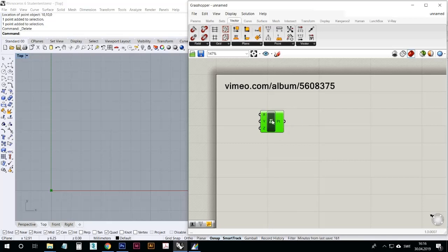Right? And after you hovered the title, I want you to hover the output so you know what it's actually giving you. If you hover here, it says point. It creates a point coordinate, and it's also giving a little bit of extra info additionally. So point coordinate, one locally defined value. That's a standard kind of phrase that Grasshopper uses. And underneath it says 0, 0, 0. So that's actually what has been produced. And if you look in the Rhino workspace, that seems to be very correct, doesn't it? But where does that come from?